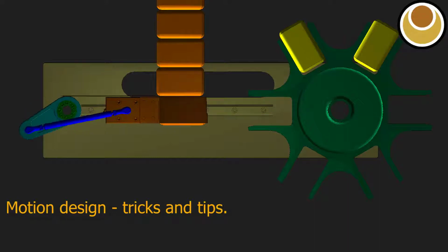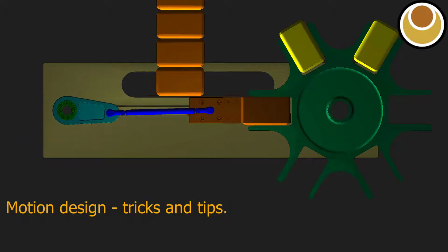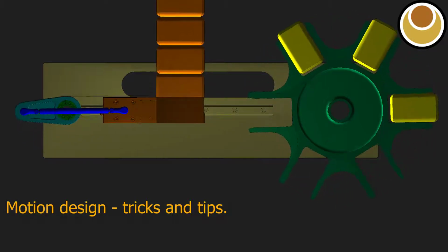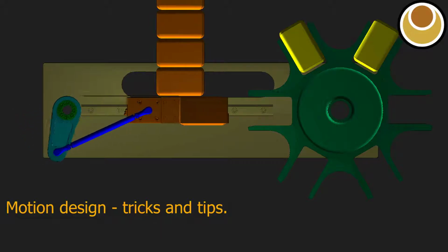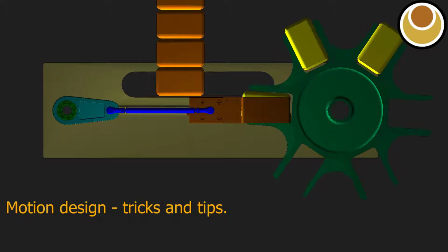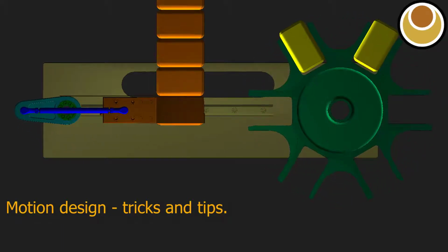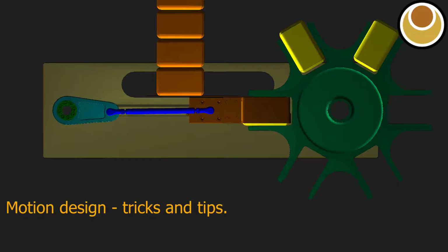In this video I want to try and explain some motion design techniques that can be applied to multi-axis machines that can improve their performance. The fundamental goal is to reduce the amplitude and frequency content of the power flowing through the machine by optimizing the motion design, implemented by cams and servo motors. This will reduce the forces and torques, giving lower overall component cost, better reliability, less noise and higher throughput.